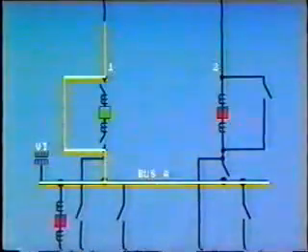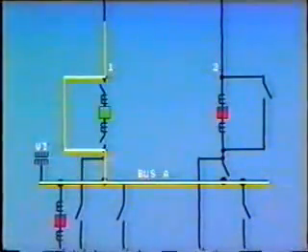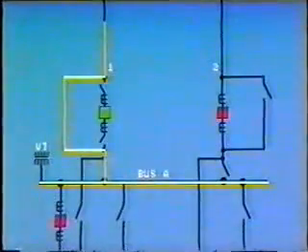The transfer bus is connected to only one circuit. Note, before closing the transfer breaker, differential protection on both buses must be disabled, as there may be a current unbalance. As previously mentioned, bus tie protection must be adaptable to all lines.